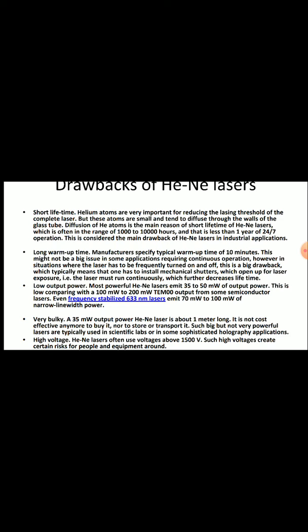However, in the situation where the laser has to be frequently turned on and off, this is a big drawback, which typically means that one has to install mechanical shutters which open up for laser exposure, whereas the laser is electrically on almost all the time. That is, the laser must run continuously, which further decreases the lifetime of the laser.